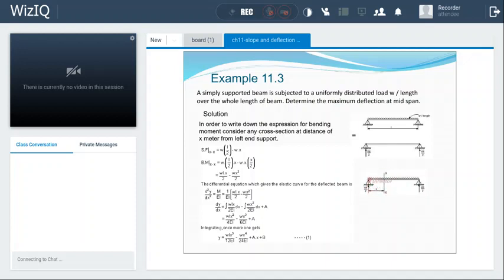So because of this force, it will be giving you a curve which is like this, taking your beam in the upward direction. Like this, because of this force. The force is upward, so it will try to lift this end, and the probable shape will be like this. When we look at the second load, this is UDL, uniformly distributed load. This uniformly distributed load is acting downward.